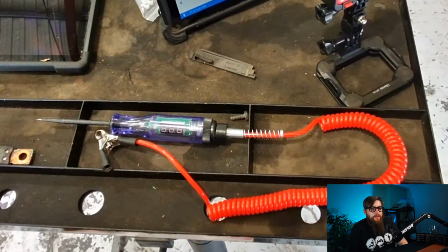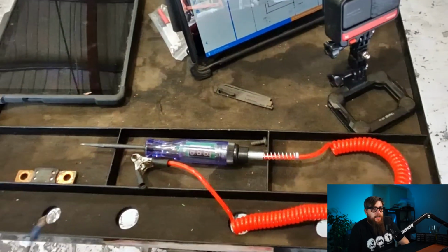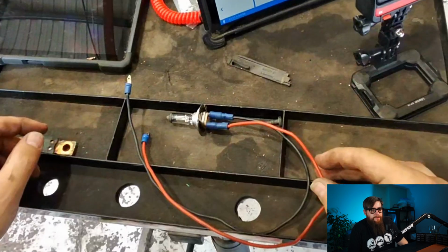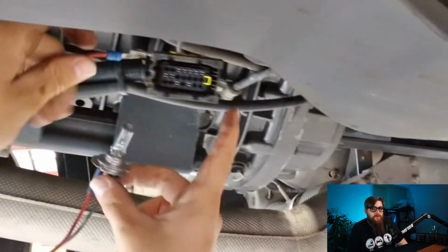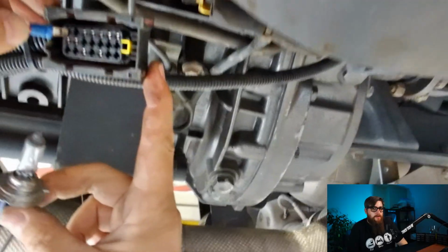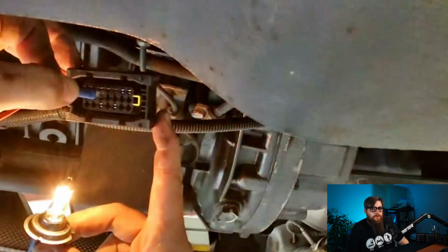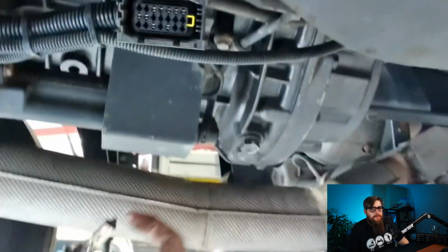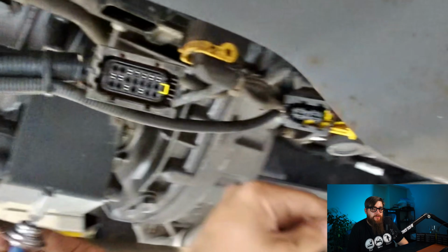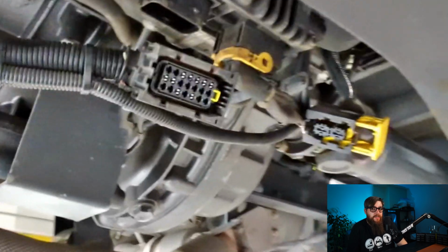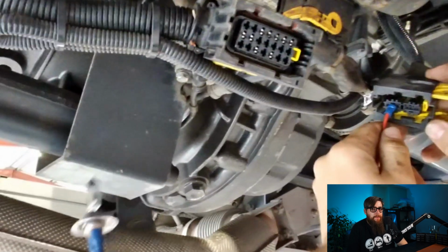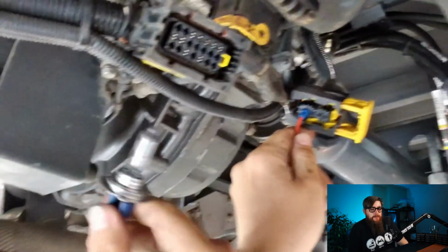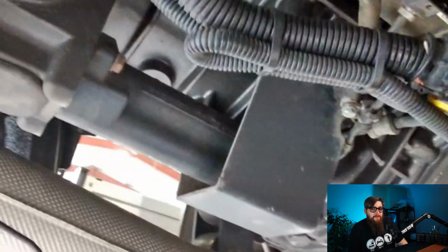Now, I do love these LED test lights, and I do find them accurate. Well, the ones I buy anyway, but you can never go wrong with a serious current draw like a bulb. As you can see from the massive inrush of current and the arc at the contact, this isn't something I'd be doing with a supply from an ECU, but seeing as these are KL30, I can get away with it. With these power supplies all looking good, I'm happy to leave this plug alone. As for our main power pack supply, further investigation is required.